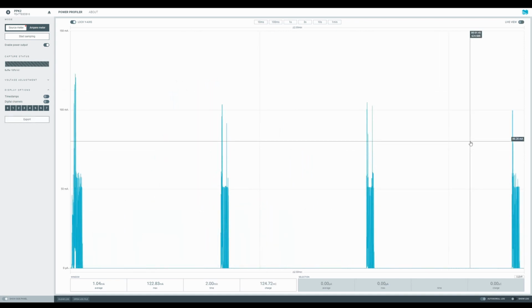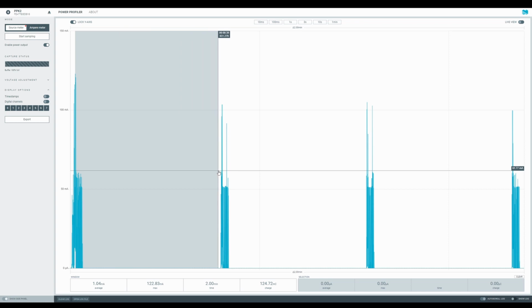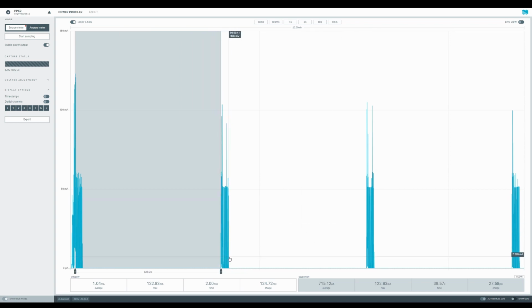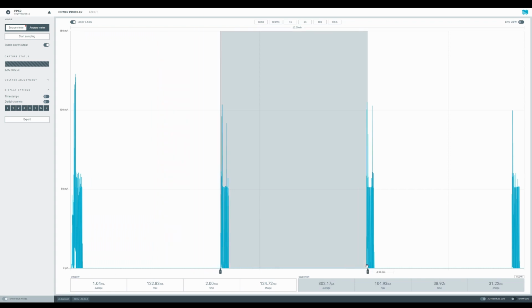So now we have captured the power profile for 2 minutes. We can see it here in the time, 2 minutes. And this is the network attached, and then we have 40 seconds between each event here. So you can see from this, the device goes to sleep, PSM mode. We see an average current of 2.7, and then for the next event, it's around 40 seconds, and then you send some UDP data again, go into RRC inactivity timer, and then go to sleep again.